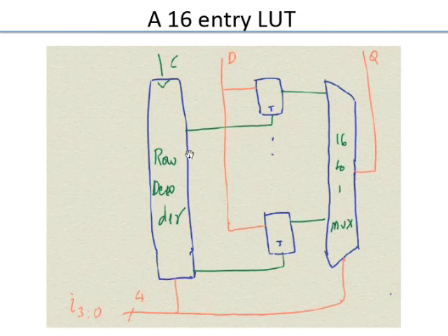Always it's on. If the clock is not there, then it's always on. It is always on, but you definitely need a write enable signal, so that will function. If we have the write enable, we need not have the clock. Exactly. So then what will happen is one of them is always in a transparent phase.